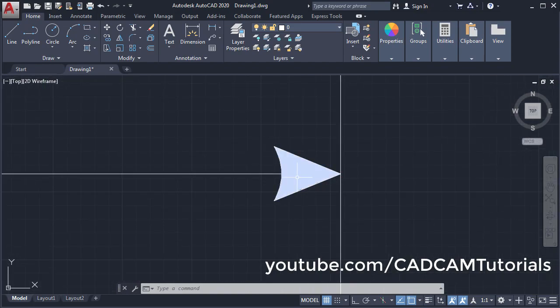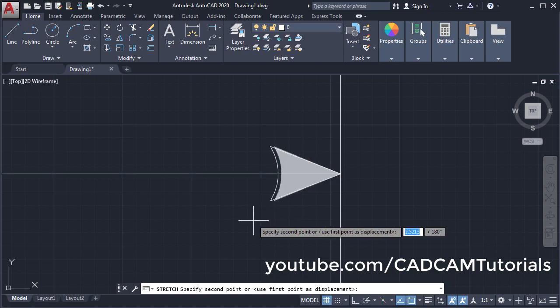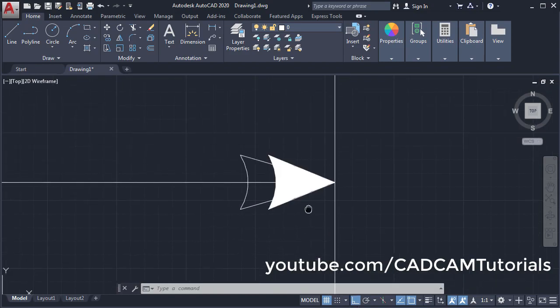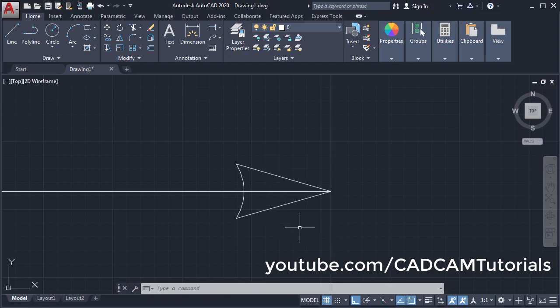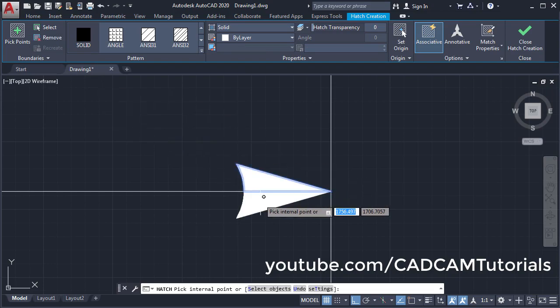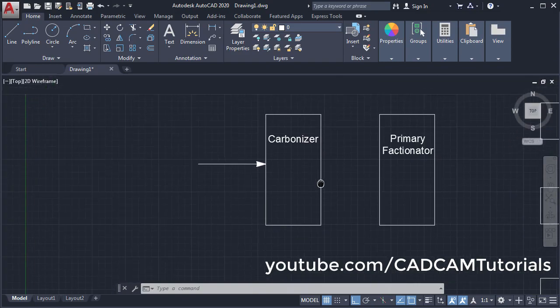So we'll adjust this arrow, we'll just stretch it outside, click on stretch, click on the right side in the empty space, take your cursor on the left side and click enter, and specify base point, take your cursor on this side, make ortho on and click and erase this hatch, enter, select this hatch, enter. We will again apply hatch, click on hatch and click inside this arrow, enter and zoom minus. Now this arrow is looking proper.